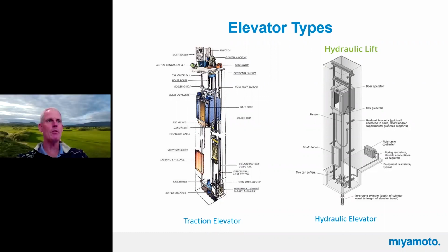Yeah, the pop-ups are always, well, they can be a challenge. If your rails can cantilever a foot or two, you probably don't need to support them up into the pop-up. But if you do, you're probably going to wind up building a steel structure, and you're going to need a hoist beam up there anyway. So you need something to attach the hoist beam to. In that scenario, you're probably going to wind up with some kind of steel frame element up there anyway.